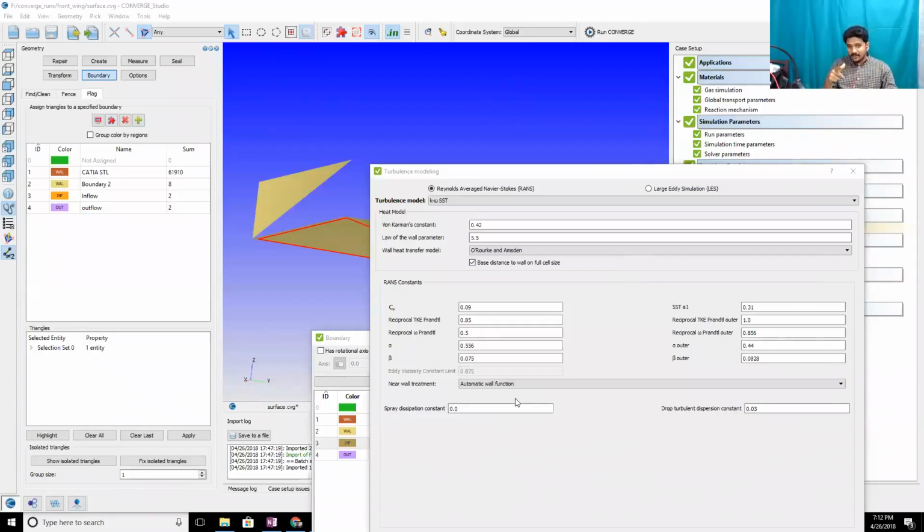And it has automatic wall functions, meaning if your mesh is too coarse, it would basically use the law of the wall model. Again, if you don't understand what the law of the wall is, for this particular workshop, you kind of have to just accept what I'm saying. Basically, it is like you giving the answer. It's a correlation with which you are telling what the answer for velocity should be, or what the answer for shear stress is. You're providing the answer.